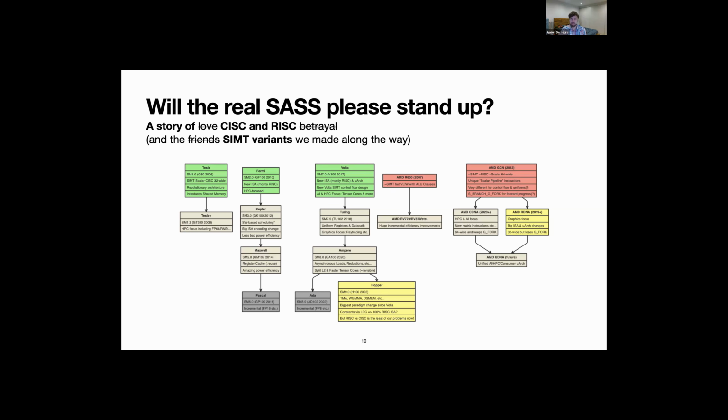So I think the amount of diversity and complexity in GPU instruction sets is really interesting. And for example, I don't know many people realize that the original G80 in 2006, the very first CUDA GPU, was in some ways really quite a CISC instruction set, like complex instruction word like x86. Not in all ways, but for example, shared memory loads and stores were part of the instruction. And these things kind of evolve over time.